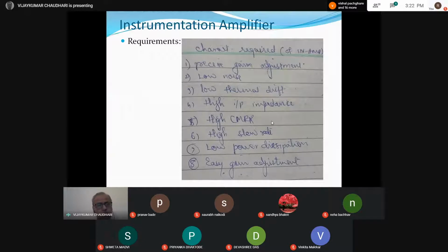Okay, so the bridge signal coming from the bridge is the differential input we are providing, whereas the other signals present are common mode signals. These common mode signals should not be amplified; they must be rejected, and the parameter that measures this common mode rejection is the common mode rejection ratio. So CMRR is given by AD upon ACM.